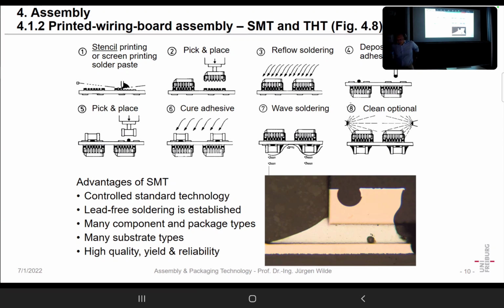And that's important. So in order to improve reliability, it's especially important if we do some protective coating on the board. Yeah, so it's not sensible just to cover the dirt you have on a board just with a layer of plastics. That's not good. Before you put that on, you must thoroughly clean it, and that's a way why cleaning is still in some applications optional.